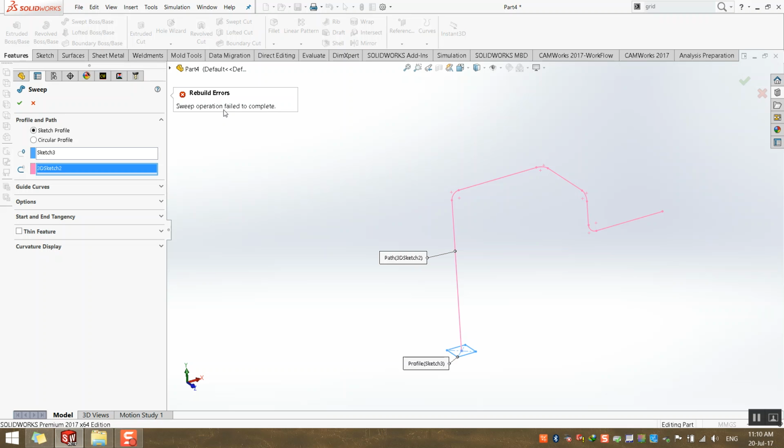If in reality you have a pipe and you need to bend it, you have a minimum radius. You have a minimum radius. Okay? Having a pipe with 20 millimeter diameter, you can't bend it on this edge.